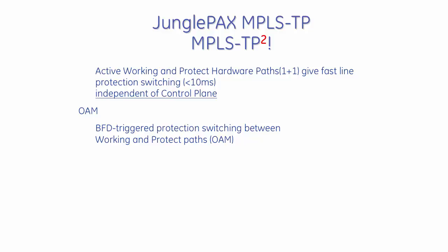With a 3.3 millisecond heartbeat and 3 heartbeat loss detection default, 10 millisecond detection periods are guaranteed. You can set the number of heartbeats you want to wait for lower. It just means that you need to make sure you're comfortable and familiar with the level of reliability of your transport. So whatever plant you're using for your wide area, be it optical or etc., you want to make sure that you don't lose heartbeats and give yourself any false positives.